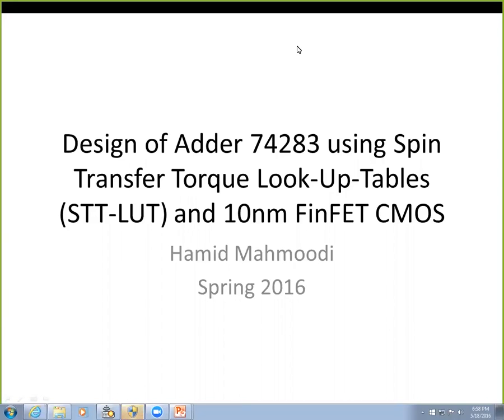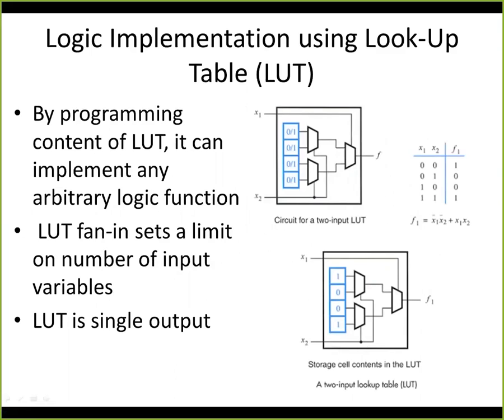The project in this course was the design of a carry look-ahead adder 74283 benchmark using a spin transfer torque lookup table in 10 nanometer FINFET CMOS. What the spin transfer torque provides us is the ability to implement non-volatile lookup tables.